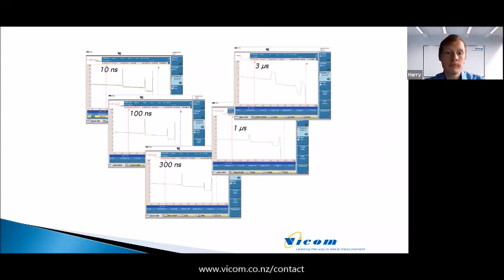Now, that smart acquisition mode I mentioned before actually combines pulses of all pulse lengths, or varying pulse lengths, together. So you can get the benefits of high resolution towards the OTDR. And as you get further away from the OTDR, you're falling away on the number of pulse widths you can utilize, and you're still going to get details on the far end of the trace as you would utilizing a 3 microsecond pulse to begin with, but you're going to have a better resolution of your trace closer to your OTDR.